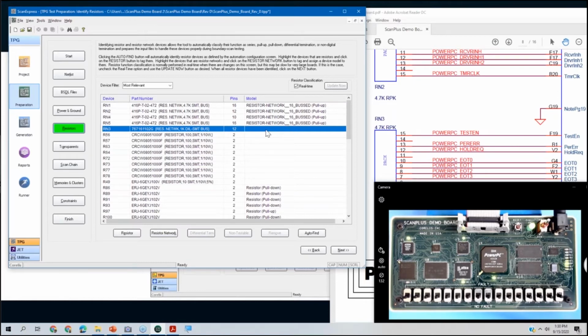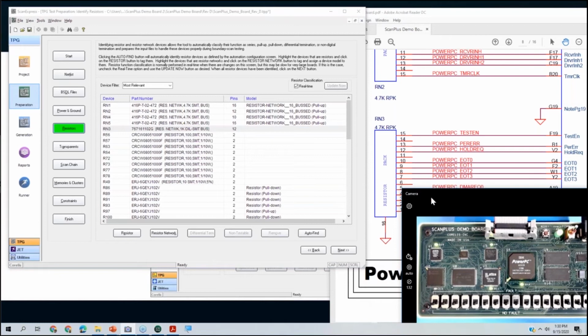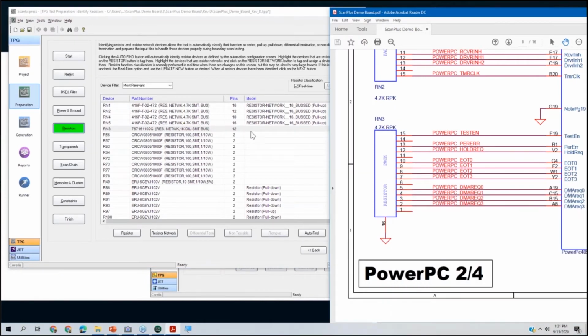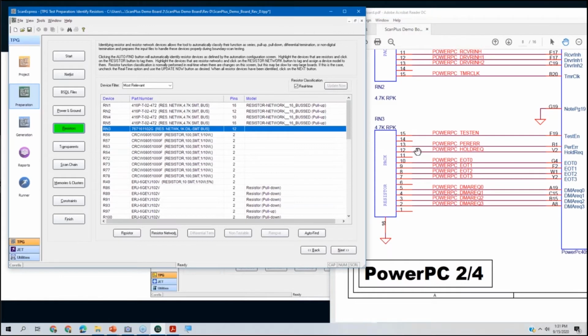It is not uncommon for us, when supporting customers, for them to say, well, it's this memory part, and then we read it electronically and we see a different ID. We say, are you sure it's that memory part? They say, yeah, that's what the schematic says, but things change and the schematic does not always get updated. So I suspect most old hat engineers have already learned that lesson. I had to learn that lesson a while back, and I figure I can share that with some others.